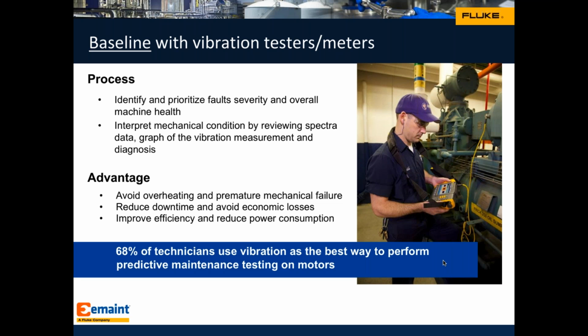I'll take an easy example of why the screening and establishing a baseline is actually critical. About a few months ago, I was with a customer. We were doing some testing and condition monitoring. And as we were waiting, I told him, why don't we walk around your facility? I know you have quite a few 30 horsepower motors. They're critical for you, and I know you have not established a baseline. So let's just take about five motors and look at the bearings on each side.